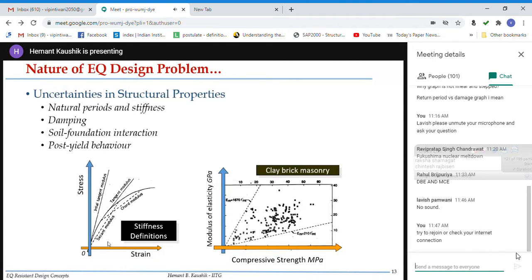that you forget about all these things. You simply calculate the modulus of elasticity for concrete as 5000 under root of fck. Here fck is the characteristic cube strength of concrete at 28 days. So you test hundreds of cubes, find out what is fck, take the square root of that, and multiply it with 5000. That will give you the modulus of elasticity of concrete.